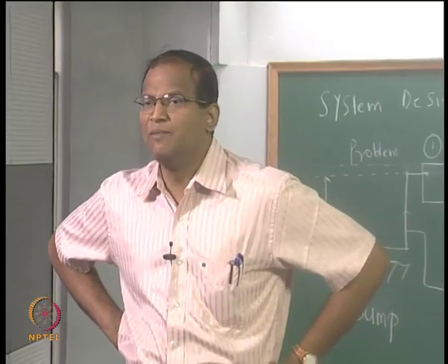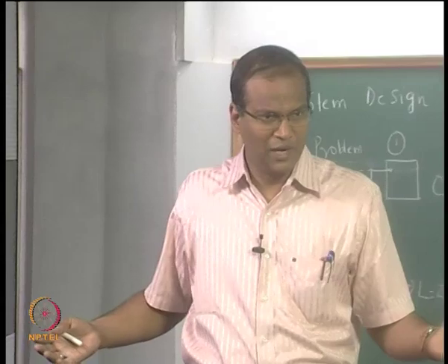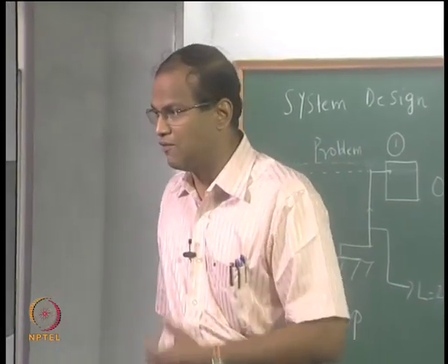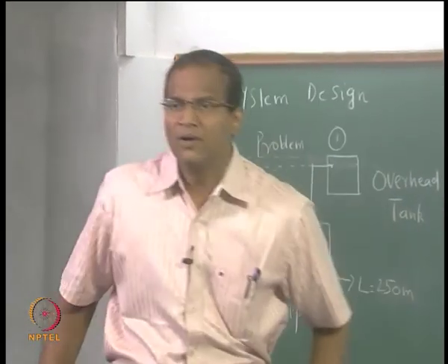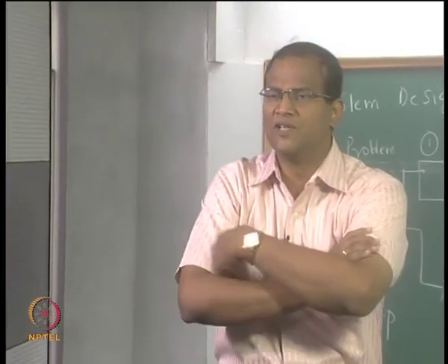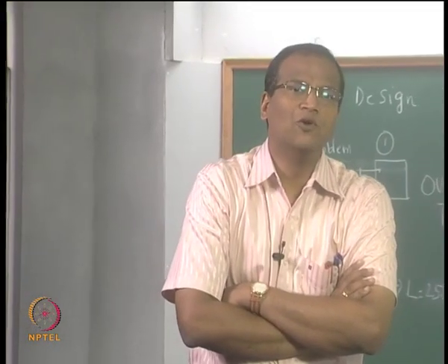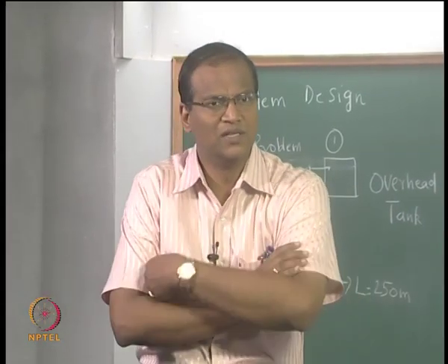You want to design a steam condenser for the 500 megawatt fast breeder reactor plant coming up in Kalpakkam. It is a practical problem. They are doing it now, right. In India we will have the plant in the next 2-3 years. You will have a 500 megawatt plant or a 1000 megawatt plant, whatever. Now you know the conditions, the pressure and temperature of the steam. Okay. So you basically know the temperature of the cooling water. You are going to get the cooling water from the sea.